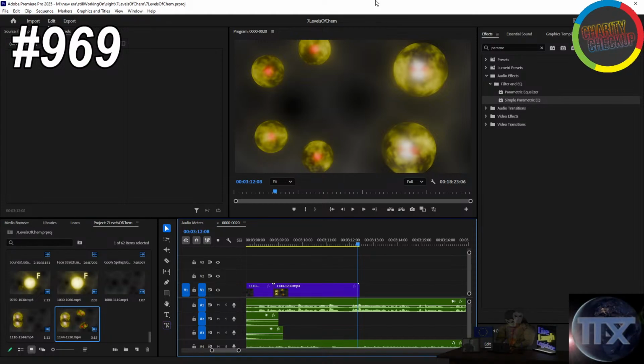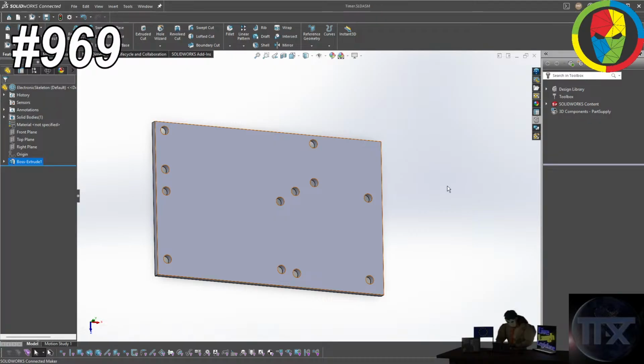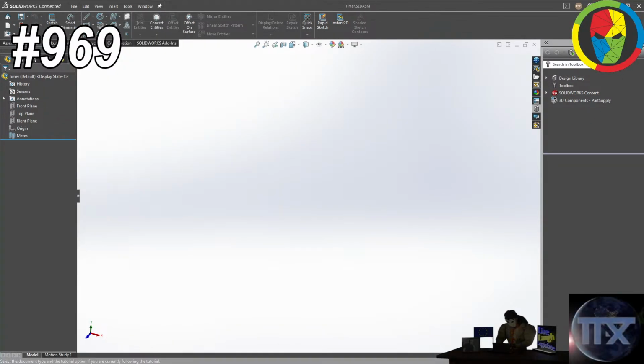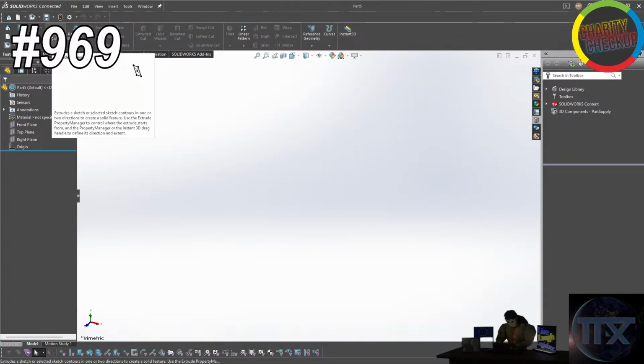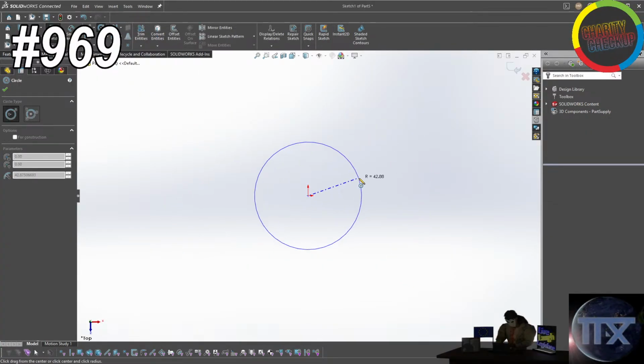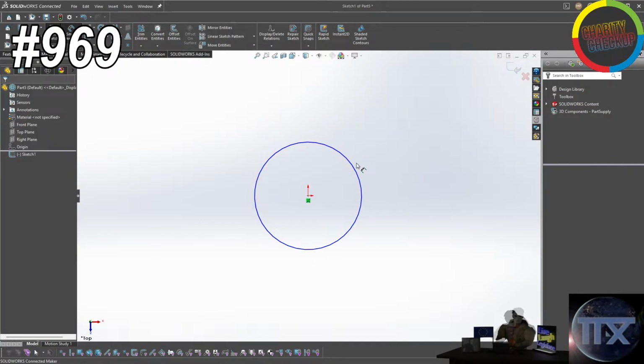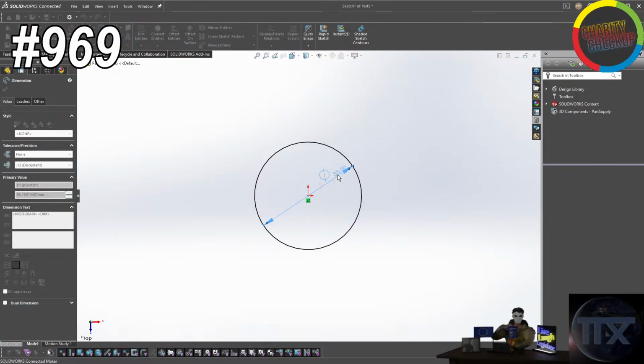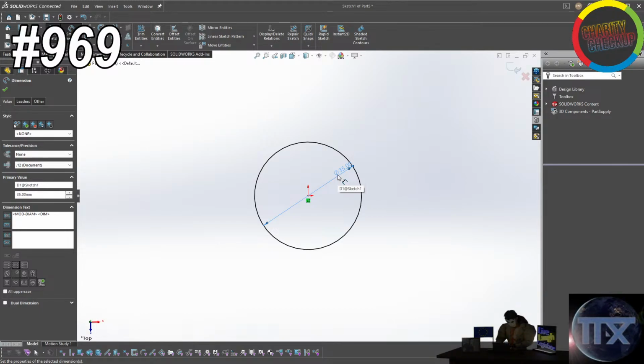I don't know. I2C data limitation throughput. Throughput limitation. What the heck? 100 kilobits a second. That's in standard. High speed is 3.5 megabits per second. It requires a special controller. Wait, but there's no how many kilobits? Well, the maximum is 3.4 megabits. Yes, but that's for specialized.